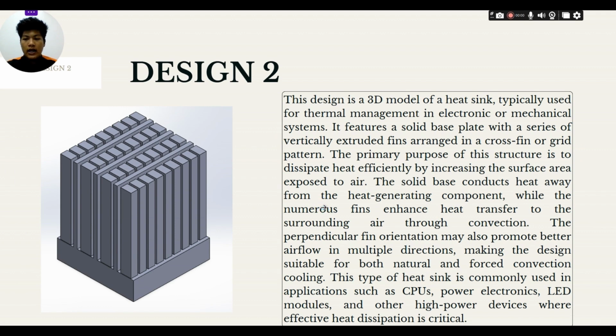The solid base conducts heat away from the heat-generating component, while the numerous fins enhance heat transfer to the surrounding air through convection. The perpendicular fin orientation may also promote better airflow in multiple directions, making the design suitable for both natural and forced convection cooling.